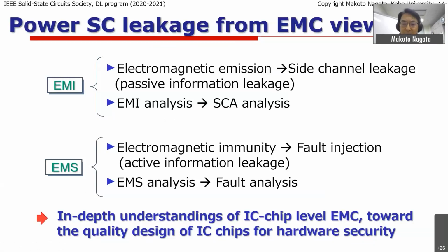Those faulty outputs can be created just by intentional injection of faults by using EM power, for instance. In this case, EMS, susceptibility analysis, can be applicable to fault analysis. And that is quite helpful for better quality design of IC chips for hardware security.